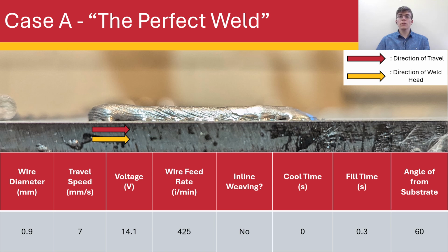Unique to this case are the travel speed, also referred to as scan speed, parameter of 7 millimeters per second, as well as the fact that there is no inline weaving. As you can see within the picture, this case has a very smooth surface finish, with a consistent height throughout the deposition.